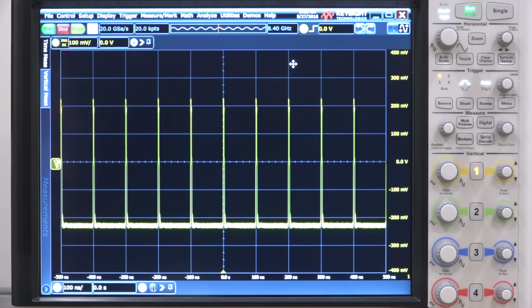Now, one of the other nice features of the Siglent SDG6000 is its ability to generate very narrow pulses. This is a 500 megahertz instrument, so I expect to be able to create pulses that have spectral content that extends to 500 megahertz. That can be very useful for some measurements that I'm about to do. But I thought it would be also nice to see these pulses on the oscilloscope first, because in reality, you should be looking at them in the frequency domain to appreciate the frequency content. Remember that a train of impulses in the time domain is also a train of impulses in the frequency domain if they were ideal zero-width impulses. Now, these are of course not, and therefore they're going to have some windowing effect on them, so they're going to have a sinc response in the frequency domain. So we will see that in a second.